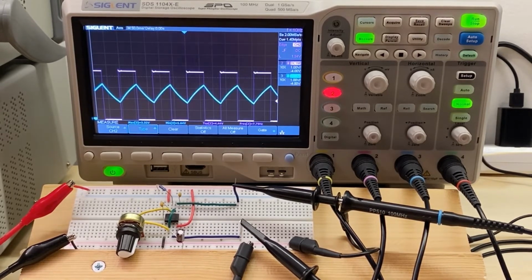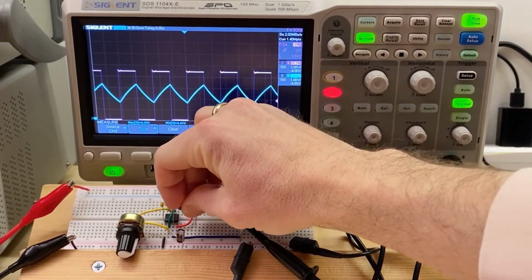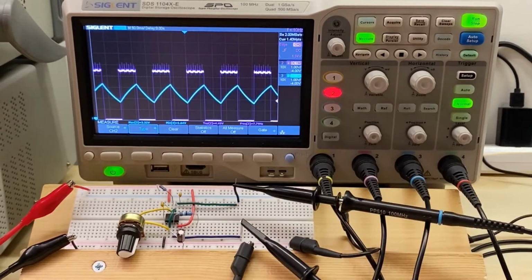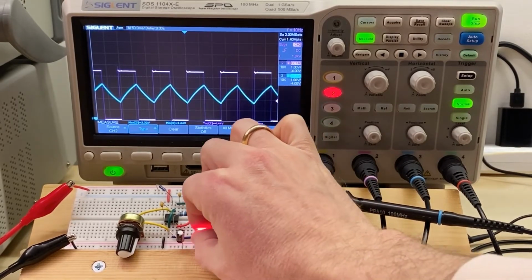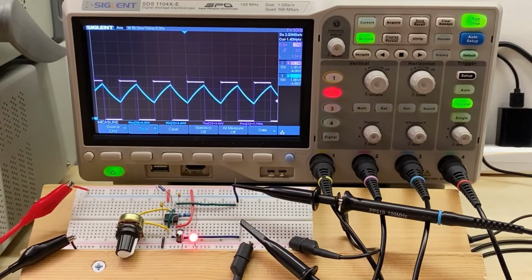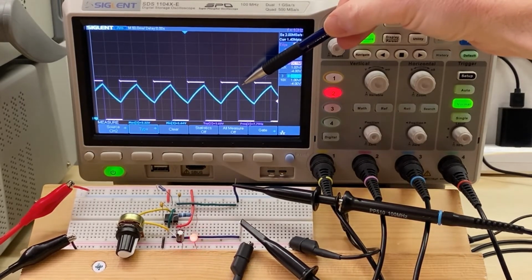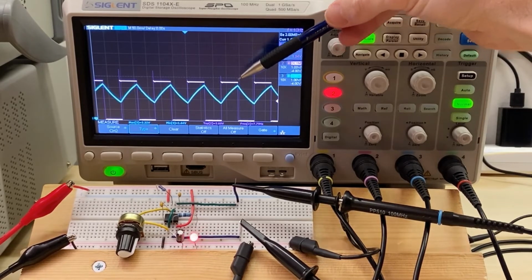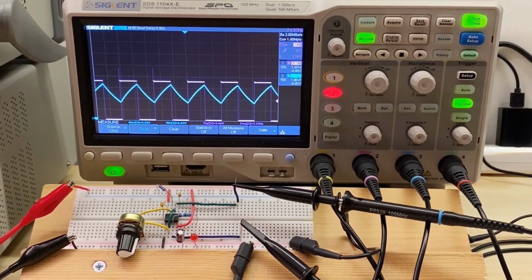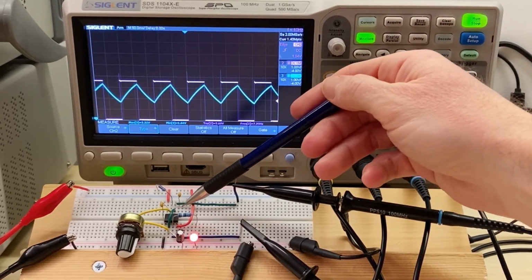Now, if we want to get a visual representation of our clock, we could add a little LED. So, of course, a current limiting resistor, and I'll do that right here now. And there we go. So our LED is blinking away, but you might have noticed that the output voltage has dropped, and it's only around 3.6 volts, even though it's supposed to be 5 volt logic. And the reason for this is that I've got the old school BJT 555 timer here. It's the NE555.